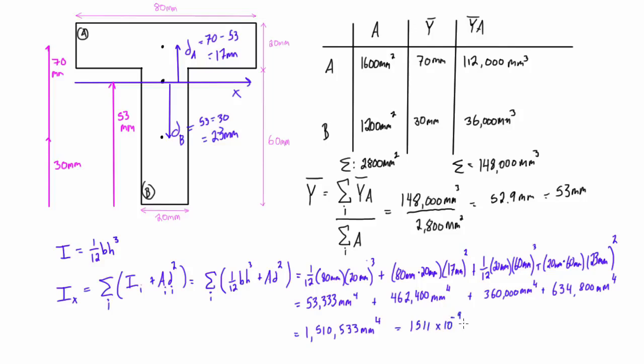We'll have this equation where the stress is equal to the internal moment times c over the moment of inertia. We're often not just dealing with square members; we'll have T-shapes or I-shapes and other shapes. So we just plug our moment of inertia in, and for calculating c, for example, we would take the distance from the neutral axis, which passes through the centroid of the whole shape.